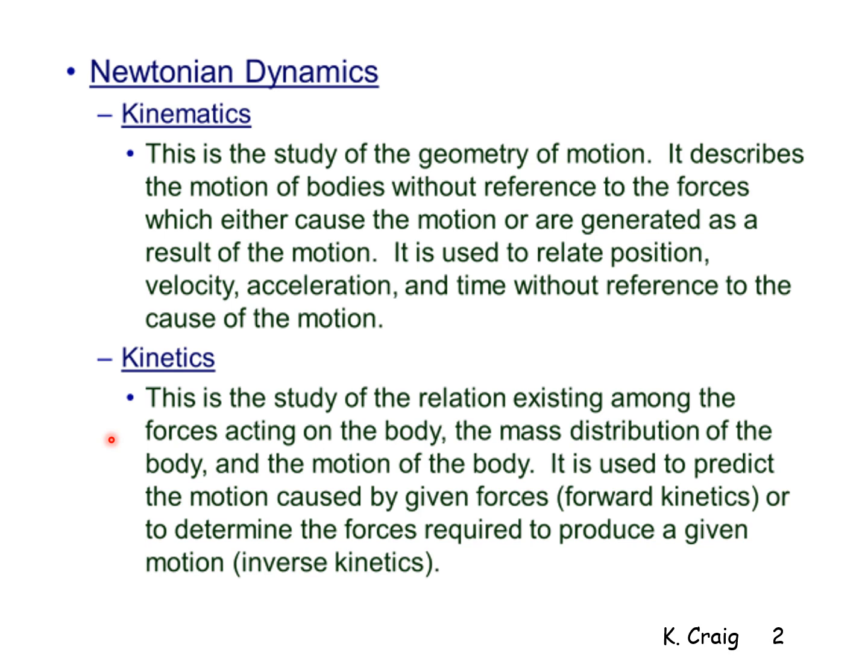Kinetics is the study of the relation existing among the forces acting on the body, the mass distribution of the body, and the motion of the body. So there are forces and torques acting on the body. The mass distribution can be specified by where is the center of mass and what are the mass moments of inertia of that body with respect to some axis through a point on the body. That's called the mass moment of inertia. And lastly, the motion of the body, as described by the kinematics. So it's the relation among those three things that kinetics deals with.